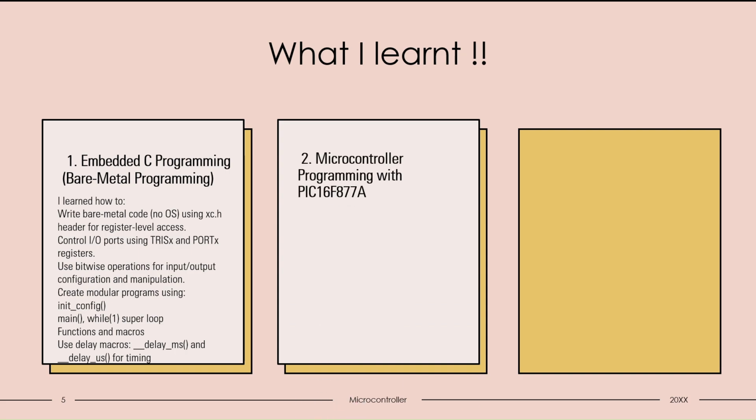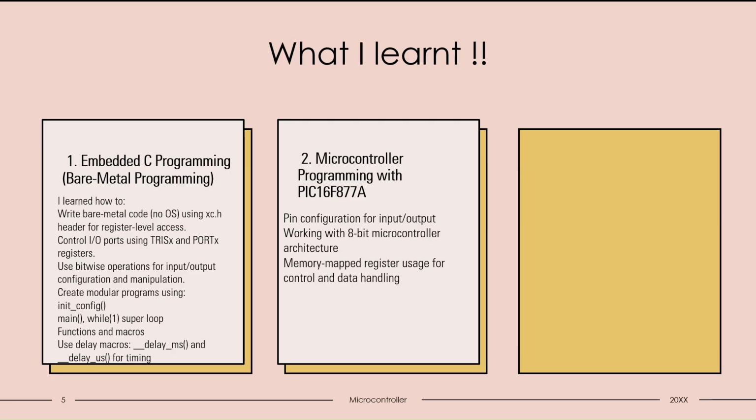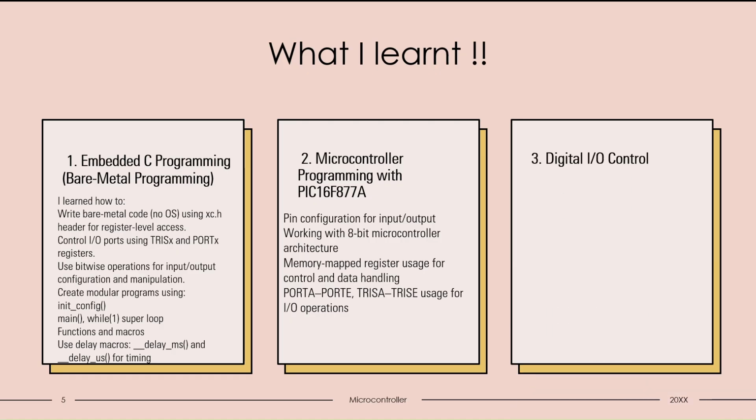Then in microcontroller programming with the PIC16F877A, pin configuration for input and output, working with the 8-bit microcontroller architecture, memory map, and registers used for control and data handling. PORTA, PORTE, TRISA, TRISE are used for input output operations. Then in digital input output control, we used LED control.